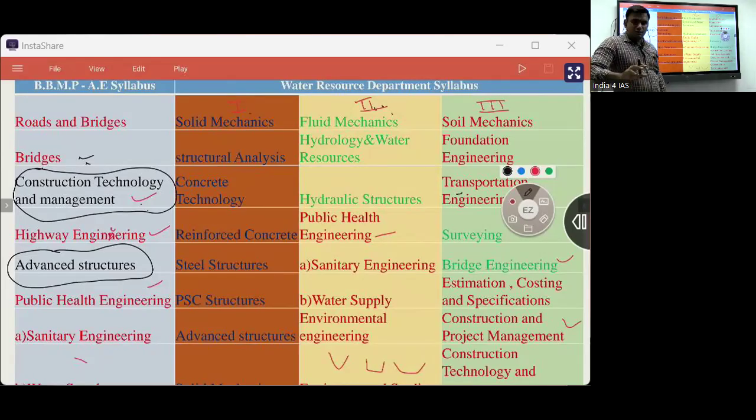So notches are of smaller dimension, weirs are of larger dimension. Practically, you cannot go for weirs in the laboratory. It's not possible. But you cannot take the same notches in the field either. You cannot measure. Those are different parameters. To correlate the field velocity to the laboratory velocity, we'll go for notches. That's it. Clear?